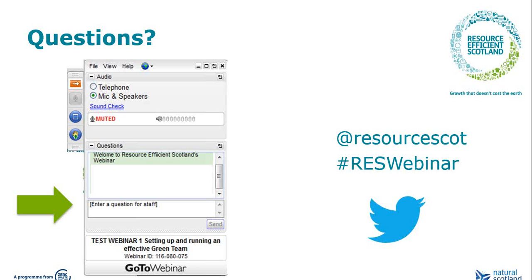One option is to have very careful placement of your detectors so that anybody entering the space, even before they've got into the space, has already switched the lights on, and sometimes in some layouts that works and sometimes it doesn't. Another option is to control maybe only half your lights on automatic controls. So you retain some lights which are switched on permanently, which provide a background level of light, and then you control the rest of the lights via the automatic aspect. And that provides both cover for the health and safety aspect and gives you energy savings as well. Okay, great. So you covering off the zoning would be really useful there.